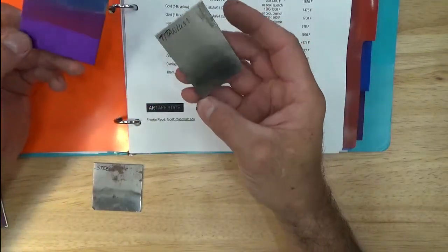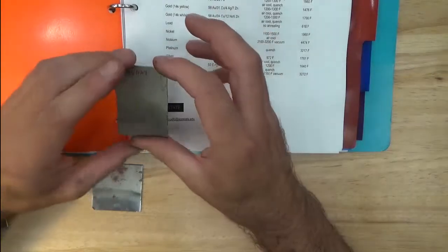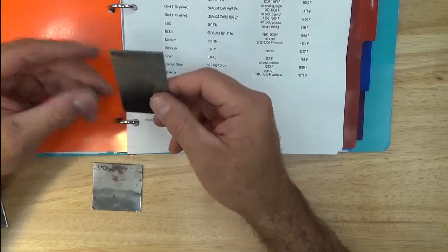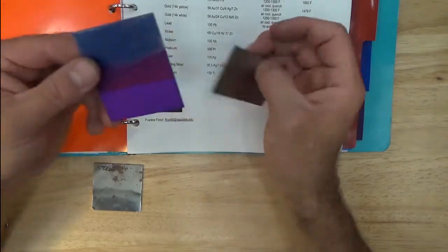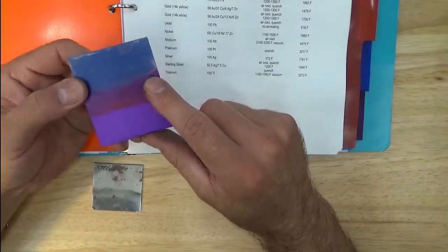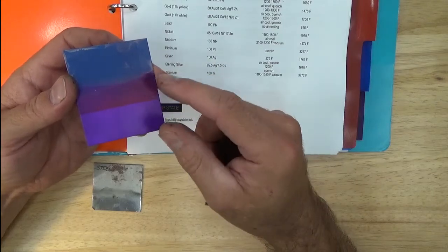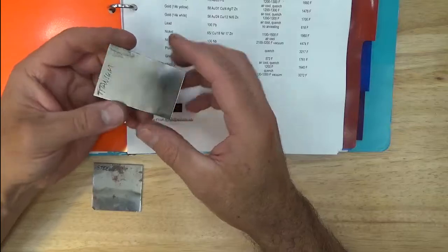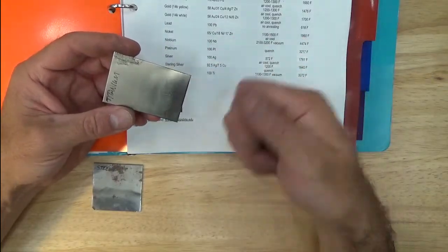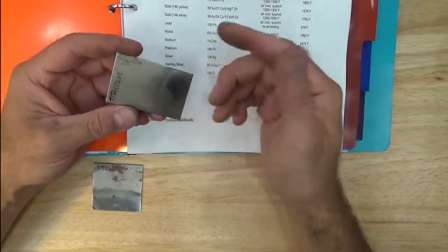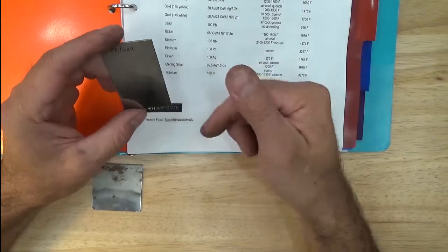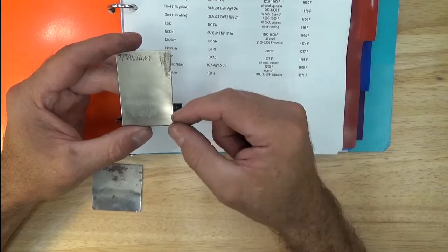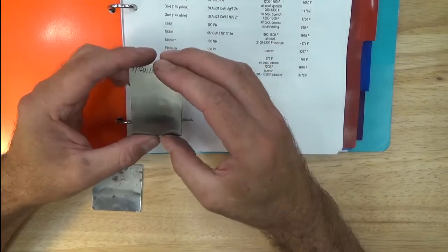Titanium and niobium can also be colored, and I'll see if I can find a piece of material that I have colored in titanium, but it's done a little bit differently. In this case, we're doing an electrochemical process for aluminum, and then we're sticking the material in dye. In the case of titanium and niobium, to color it, you could use a torch to heat it, and it would actually change colors that way, or you could do an electrochemical process, but the voltage of the current that you're running through is what gives you a spectrum of colors.